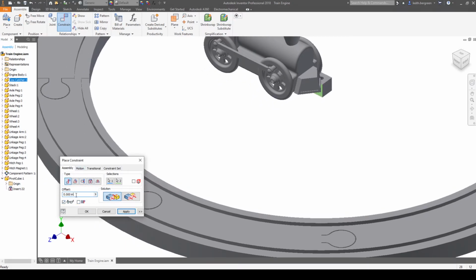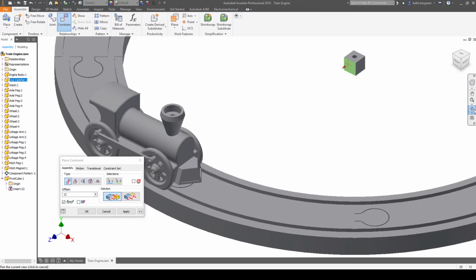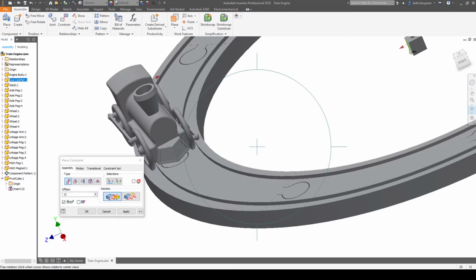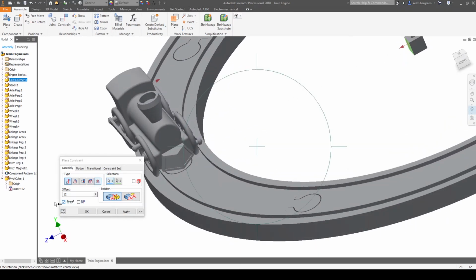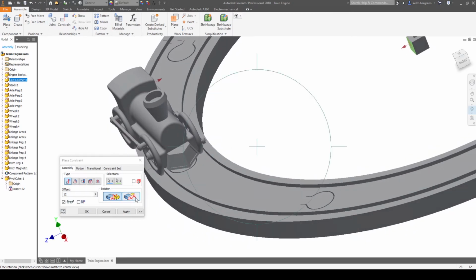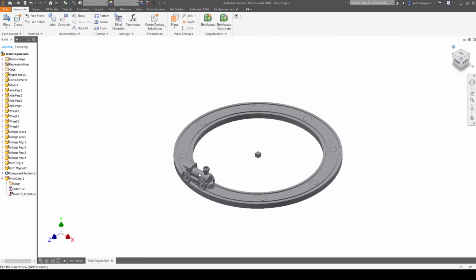So we're just going to apply an offset, and we're just going to change this to about 12 inches, which should place it approximately where it needs to be, apart from the pivot cube. This dimension is just a rough estimate, so you can go back in and change this later to fine tune this so that the wheels are lined up with the grooves. Okay, so go ahead, click apply, and then exit out of that, and then we'll just test this again.